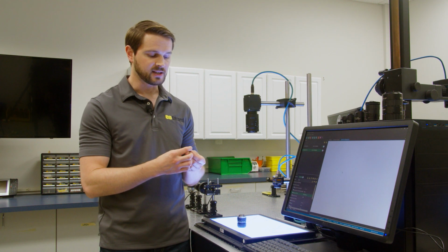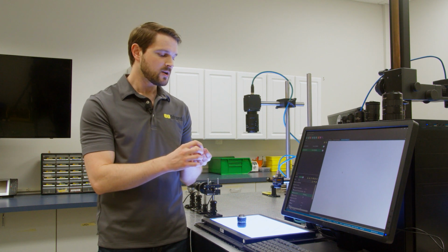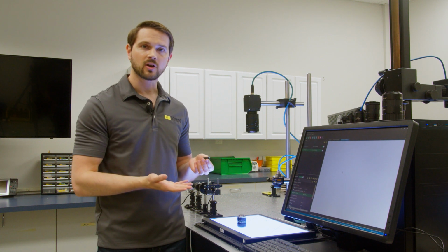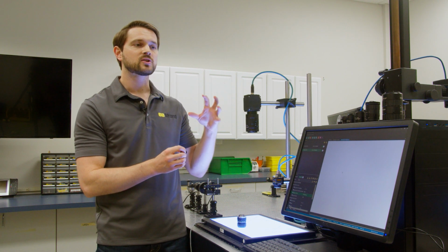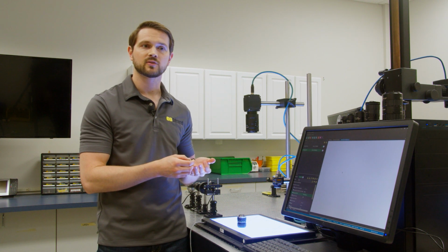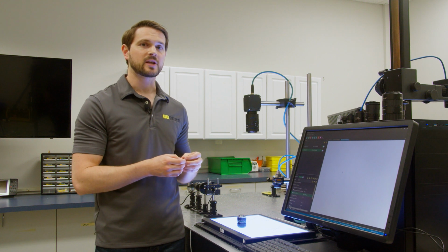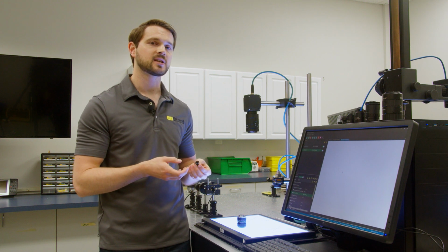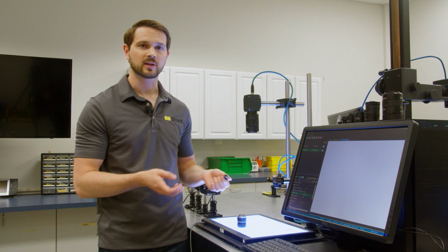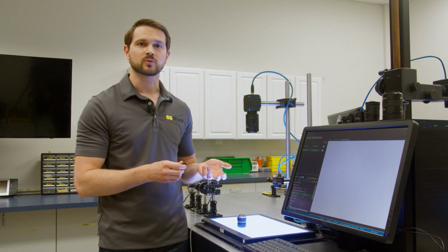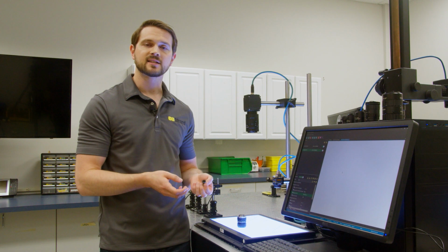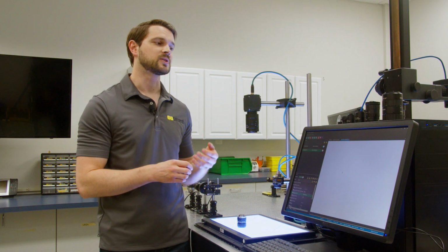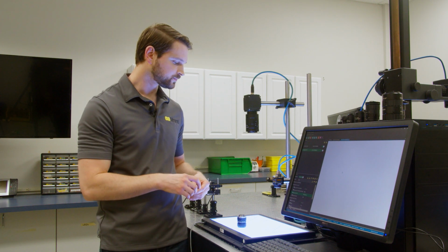Lenses are obviously round, which means they output images that are also round or circular. So we need to make sure that the sensor we're designing the lens for will fit inside what we call our image circle. Most of the time you won't hear the term image circle outside of the optics realm, but you can see it sometimes, especially if you're using line scan sensors. You might be able to spec a lens with respect to its image circle.